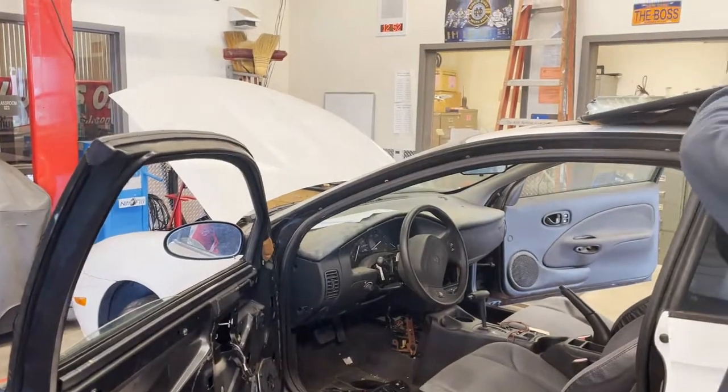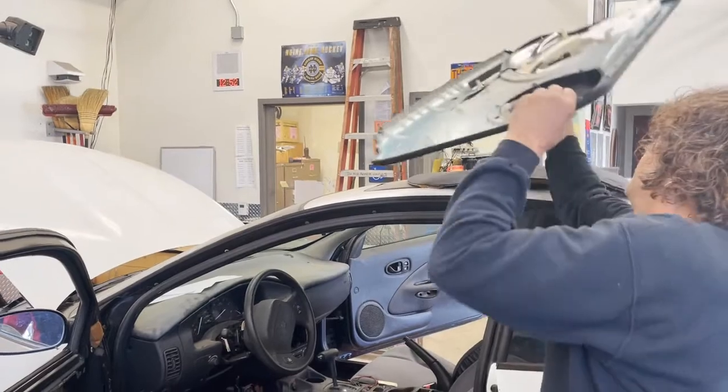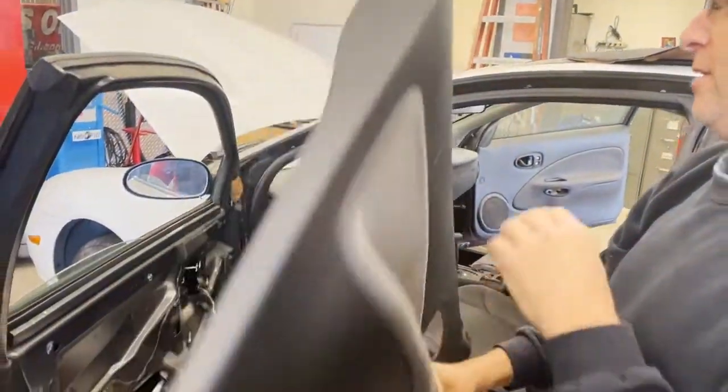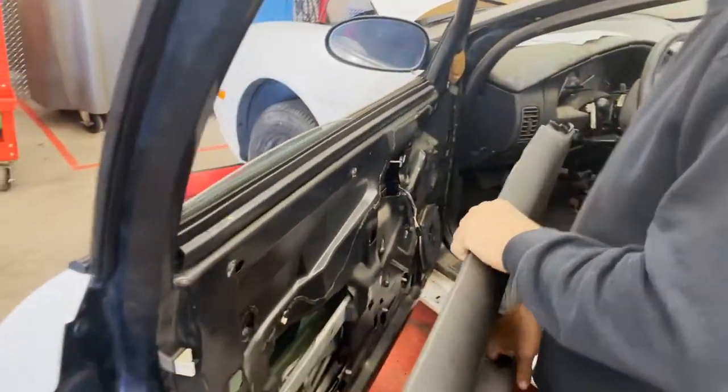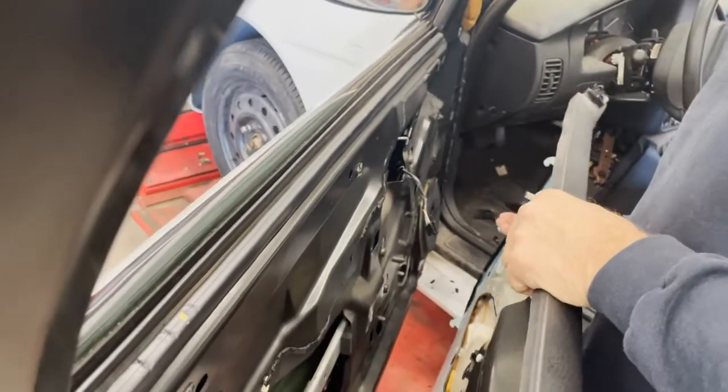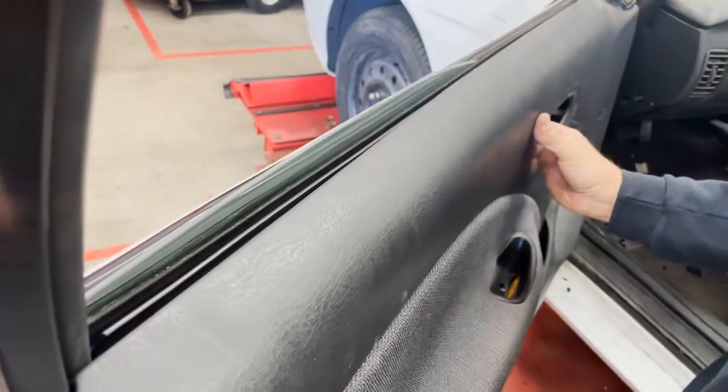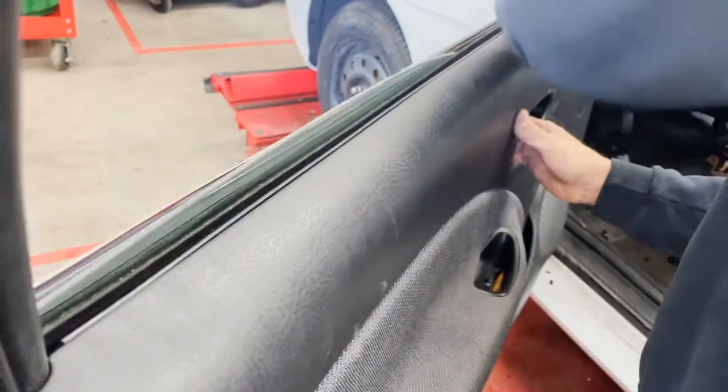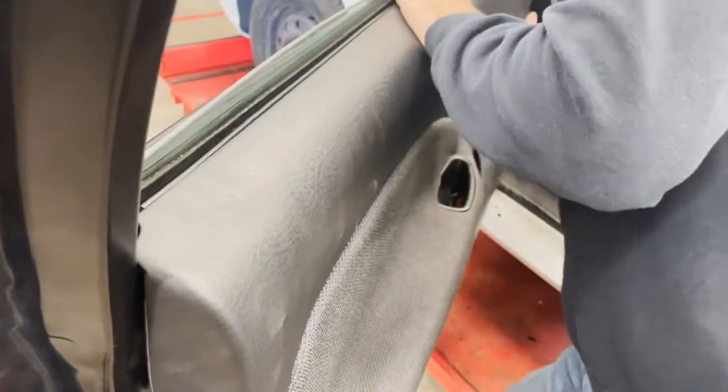Okay, so we just have to put the door panel back on. I'm just going to do it in the reverse procedure, the way I took it off. The last thing I took off was the panel, but I want to make sure that this wire comes through so I can connect it to my power door lock switch. So this just hooks on the top. And once you get it lined up, oh, and don't forget, there's like a hook clip on here that I have to actually lift this up, hook that in.